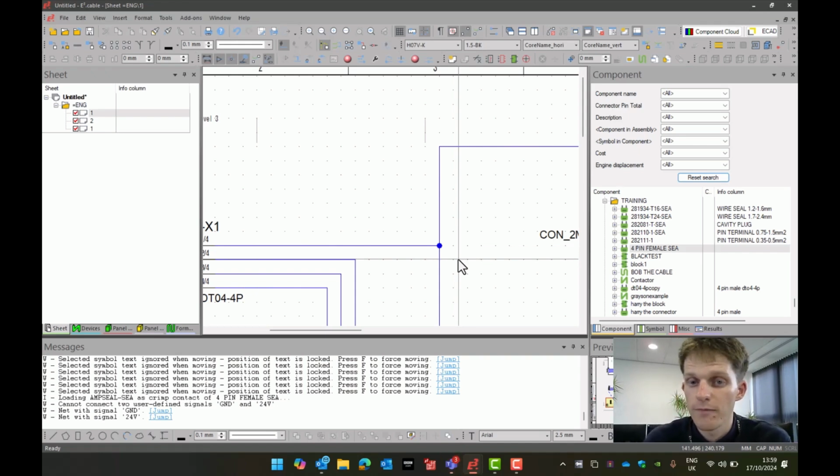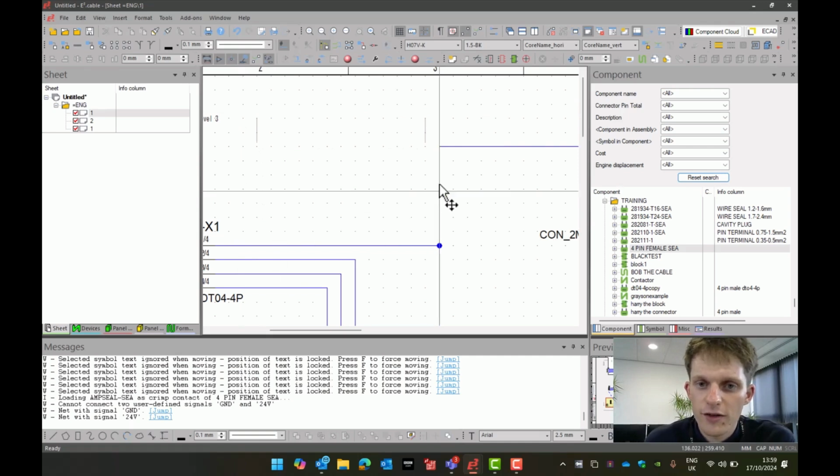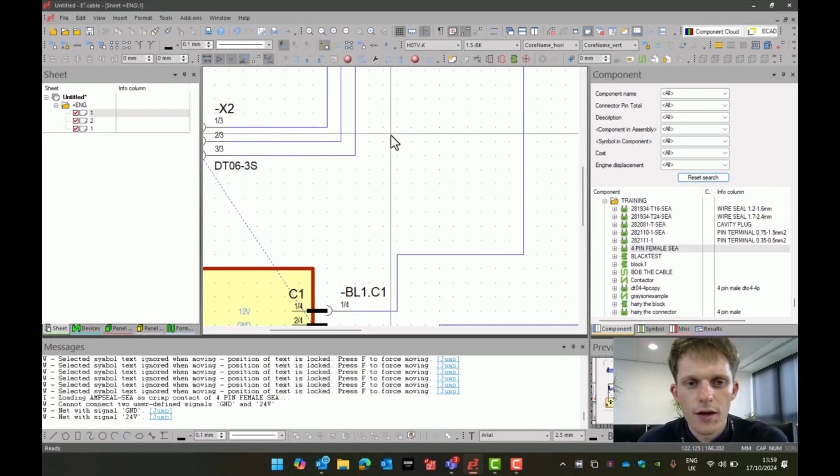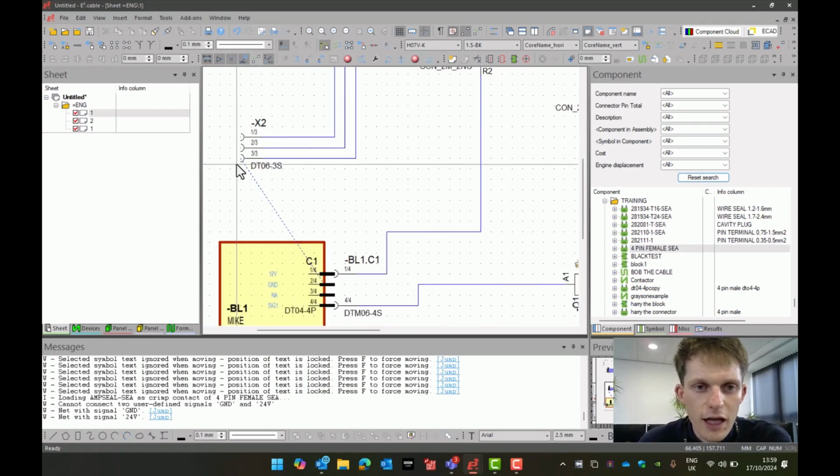So I could place stuff onto it, or if I were going to have 2 wires associated with this line here, I could use my angle counterclockwise and angle clockwise tools here, okay? They allow us to define a direction for a wire connection, and we'll show you that a bit more later on. As we can see, if we have signals which are common, they will then follow through.